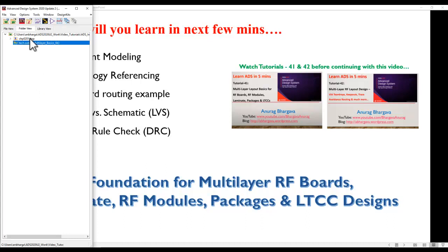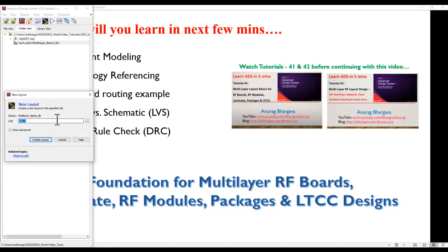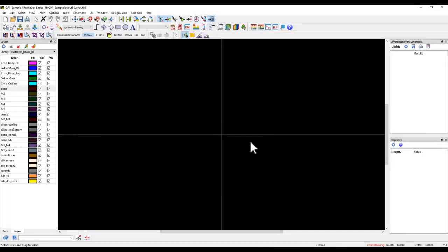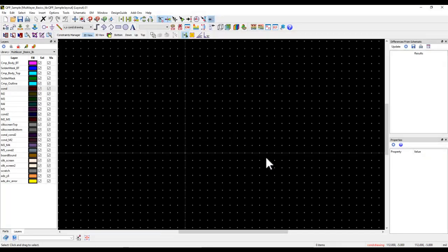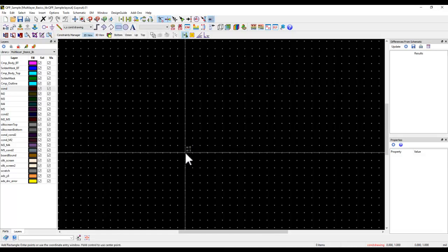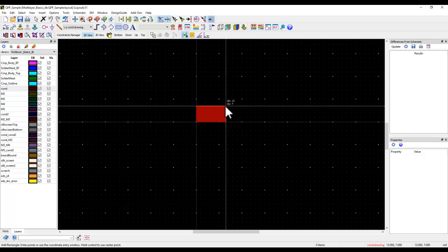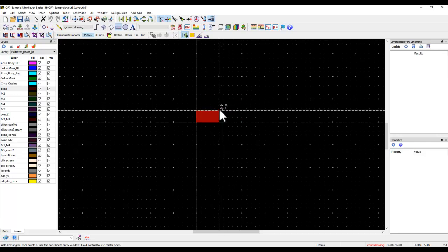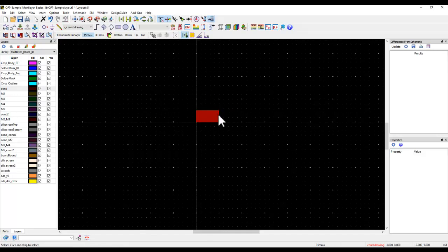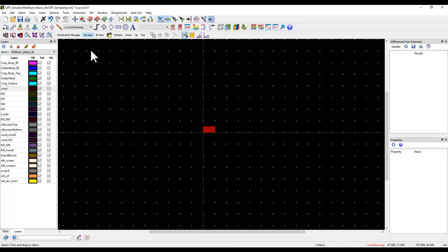Now, just for the variety's sake, I'm going to show another footprint, and let's use a QFP, quad flat pack kind of thing. And let me create QFP and call this a sample. Now for QFP kind of structures, you need an array on all four sides to create a footprint. So here, using the same knowledge like we did earlier, I'm going to create a rectangle. And again, this rectangle, I'm going to create something like 10 by 5, for example. I find it easier to work in a grid, but then again, as I said, if you don't find it convenient, always use the coordinate entry.